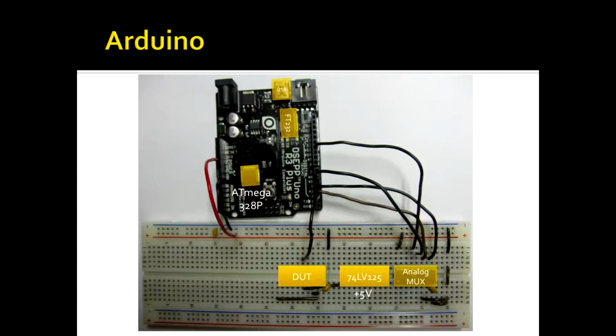So for a while, I seriously considered Arduino for about 7 minutes, because why not? And the problem with Arduino is the crystal is fixed on board. I think it's 16 megahertz. And as soon as you use any of the timer or output compare registers to divide that clock down, you can't take the 16 megahertz and provide it directly as 16 megahertz on an output pin.